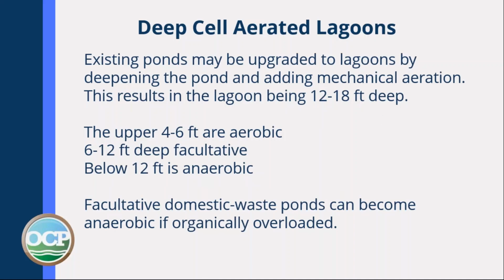Deep cell aerated lagoons. Existing ponds may be upgraded to lagoons by deepening the pond and adding mechanical aeration. This results in lagoons being 12 to 18 feet deep. The upper 4 to 6 feet are aerobic. The next 6 to 12 feet are facultative. The bottom of the lagoon is anaerobic. Facultative domestic waste lagoons can become anaerobic if organically overloaded.